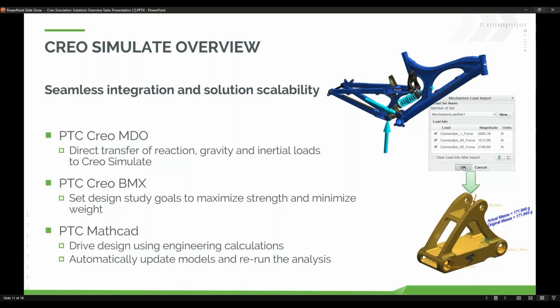PTC now comes with MathCAD. All PTC licenses have a MathCAD Express built into it. And so you can go in and you can use your MathCAD. You can use those design engineering calculations, and you can use those calculations to update your model. So once you have numbers from Simulate, you can tie those into MathCAD, and then you can have MathCAD drive your model.